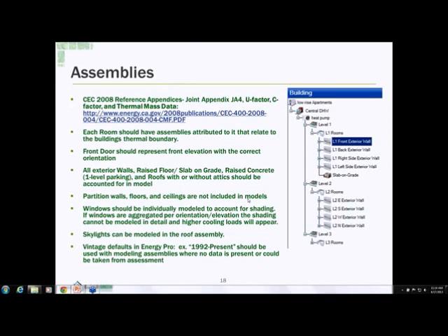So there are 2 different tabs: residential mechanical ventilation and actual exhaust fans. But you can email me at the end, and we can maybe go into how we can work on non-res and exhaust fans. And yes, you want the total CFM, so add up all the CFMs. And I think for the horsepower, you want to average it, but you want the total CFM.